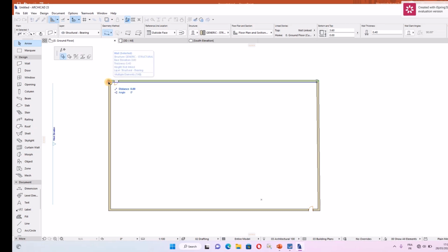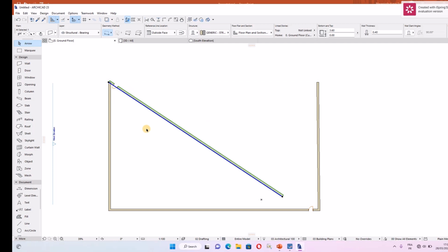So once you again press it there, then there comes a symbol like this, which is rotate. So we can rotate our wall. For example, I can click here. Then once I click here, there comes this symbol. So I'll first click on this wall, then choose the line along the rotation from. Then maybe I want to do it along this line. Then you can choose the rotation where I want to rotate it up to. So it's now like this. So let's press Ctrl Z for undo.